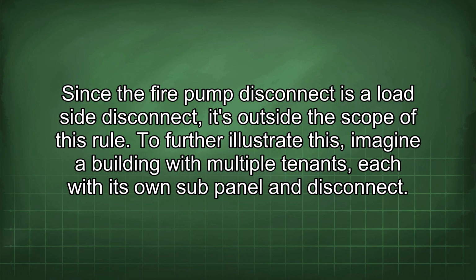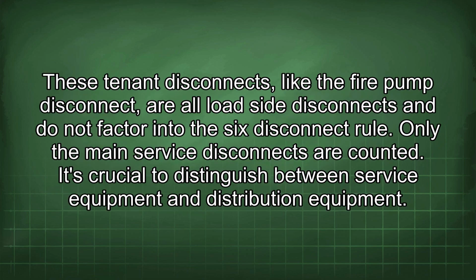To further illustrate this, imagine a building with multiple tenants, each with its own sub-panel and disconnect. These tenant disconnects, like the fire pump disconnect, are all load side disconnects and do not factor into the 6 disconnect rule. Only the main service disconnects are counted.